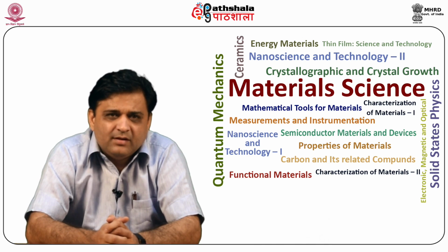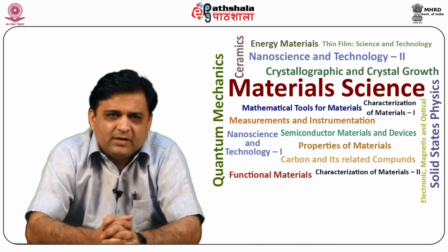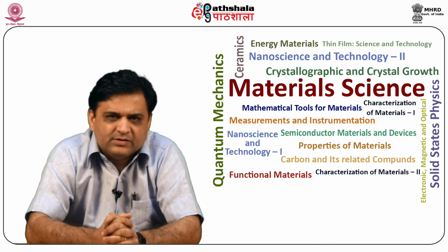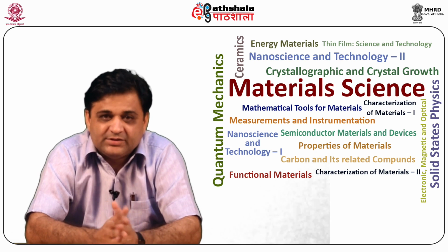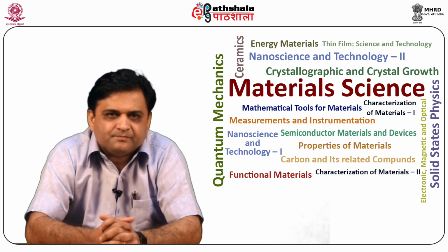So chemical vapor deposition. What is chemical vapor deposition? Deposition can also take place due to a chemical reaction between some reactants on the substrate. In this case, reactant gases, which we call precursors, are pumped into a reaction chamber or reactor. Under the right conditions, meaning temperature and pressure, they undergo a reaction at the substrate.